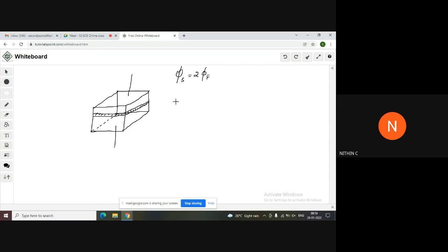So while strong inversion happens, what is actually happening? If we take the structure of the MOS cap like this, we have a metal part at the top, an oxide layer here. The shaded region is the oxide layer. This will be the three-dimensional structure of the MOS. So you have a metal part, you have an oxide layer, and finally you have a semiconductor part. The third part is the semiconductor part. If we take the semiconductor as p-type, the expected carriers over here are the holes, right?